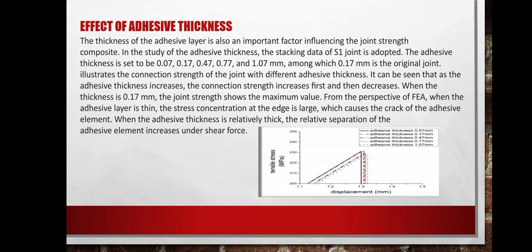From the perspective of FEA, when the adhesive layer is thin, the stress concentration at the edges is large, which causes the crack of adhesive element. When the adhesive thickness is relatively thicker, the relative separation of adhesive element increases under shear force.